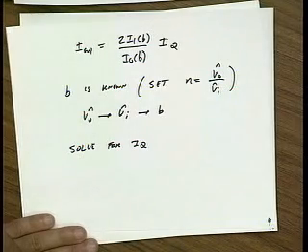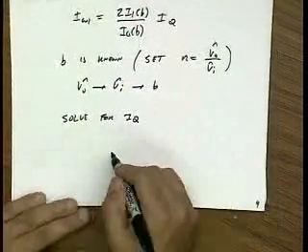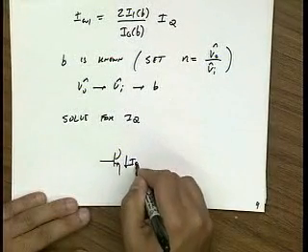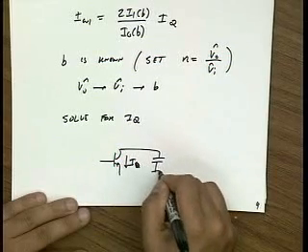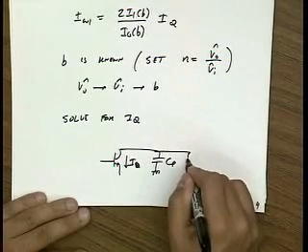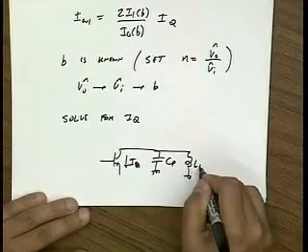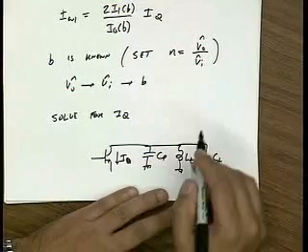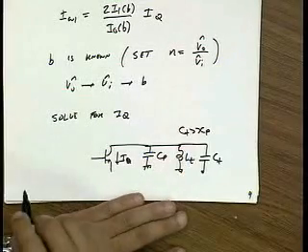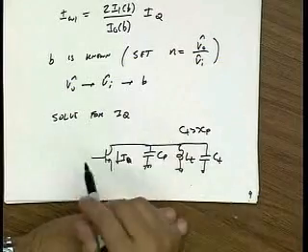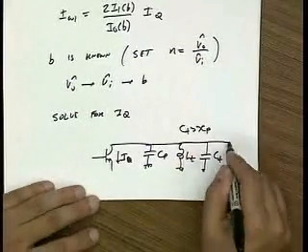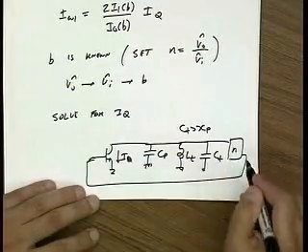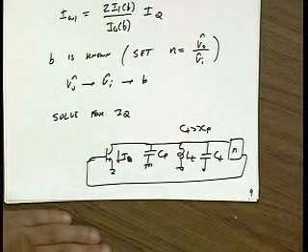So pretty much you can see now that the design is done. So coming back to the circuit, IQ is known. There's going to be some parasitic capacitance here. I'm going to put in my tank, my inductor. I'm going to add some tank capacitance basically to dominate over the parasitic capacitance, because the parasitic capacitance will vary a lot over process. And then I design my feedback network, which is the N factor.